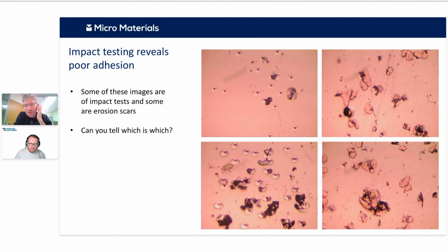But equally, the thing about increasing hardness, we can also use this type of test to look at the effect of, or simulate, a shot peening process. It's not just related to erosion. There are a number of other applications. People have even suggested micro pitting, also interrupted cutting situations. There's quite a lot of different applications.